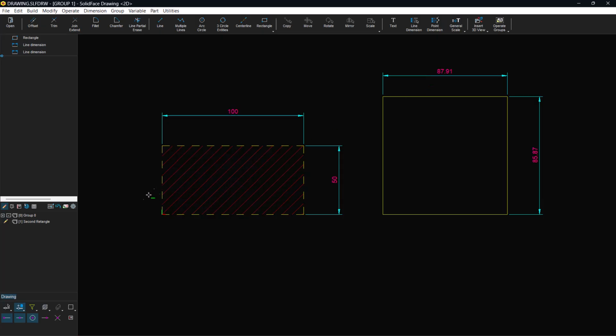In the group list, Group 1 is shown with a pencil icon indicating that it is the active group. To facilitate visual identification of the active group, moving the mouse to the lower area of the screen opens a View Options bar. There is an option to view all passive groups with a single color called Passive Color. Clicking on this icon activates the option to display all passive groups with passive color.